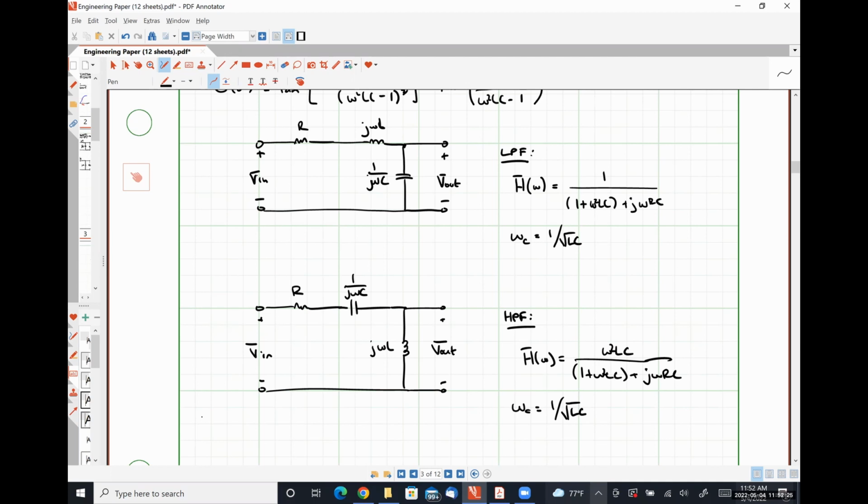And then let's see, your starting frequency. So if we're trying to hit something in the ballpark of 100 megahertz, you would start your sweep somewhere in the ballpark of 1 hertz and end it somewhere in the ballpark of 1 gigahertz. And that should give you a good picture of everything. Those would be the settings you'd use.